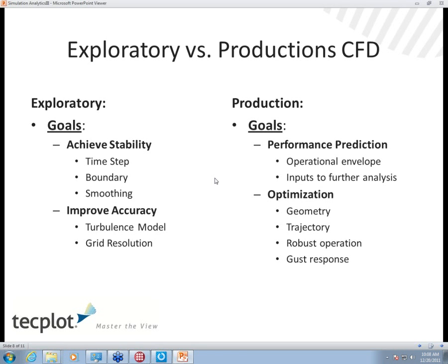So you have to play with it a little bit on the particular geometries you're dealing with. There are some things you might need to alter to get a robust solution. You might want to alter your time steps, certainly if you're running an explicit scheme, but implicit schemes as well. There may be a time step beyond which it's unstable.